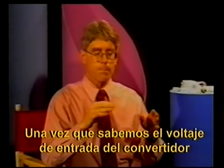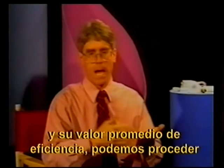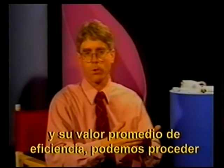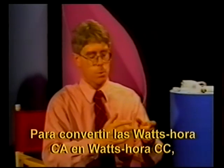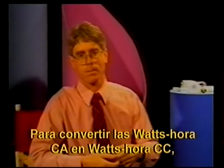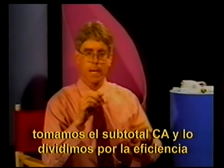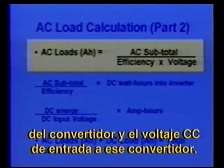Once we know the input voltage to the inverter and the average value of efficiency for that inverter, we can proceed with the rest of our AC load calculation. Because what we've got to do is convert AC watt hours into DC watt hours. The way we do this is we take our AC subtotal and we divide it by the inverter efficiency and the input DC voltage to that inverter.